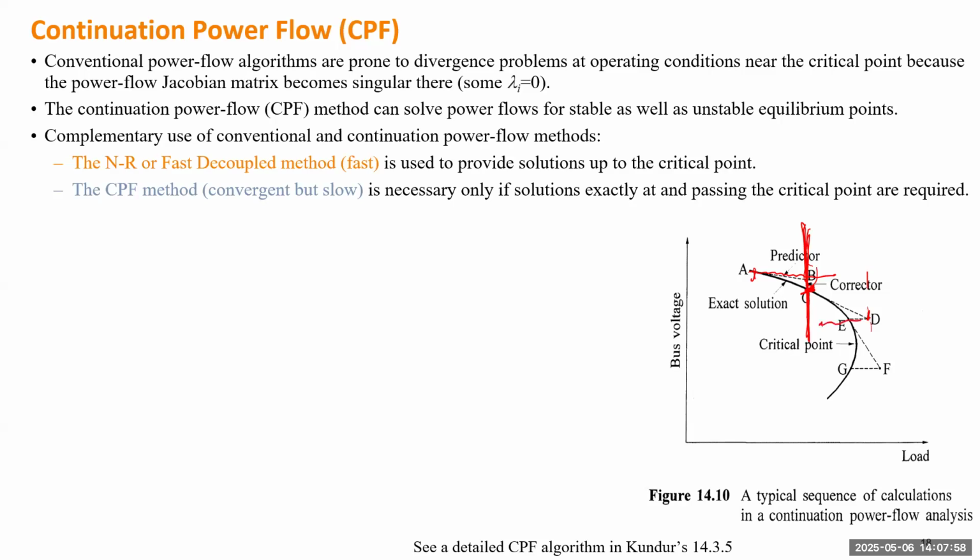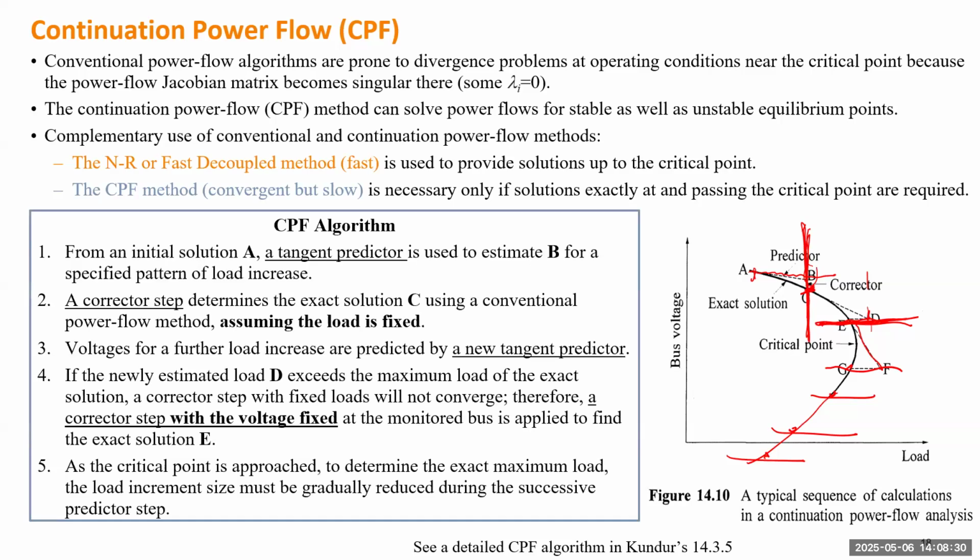Then you have to assume a different load model with constant voltage but arbitrary load. Okay, that is more aggressive than a constant impedance load. So that can guarantee this load characteristic will be able to intersect with the PV curve. So beyond that point, every time you basically just draw the load characteristic as a horizontal line with constant voltage, and that can guarantee it intersects with the PV curve. Okay, so I put some detailed algorithm into this box. I won't go through this box, but just give you an idea.